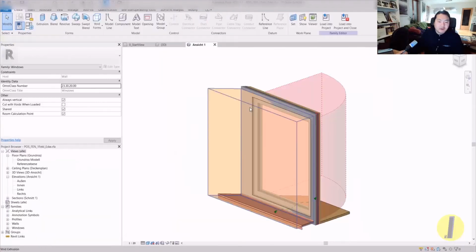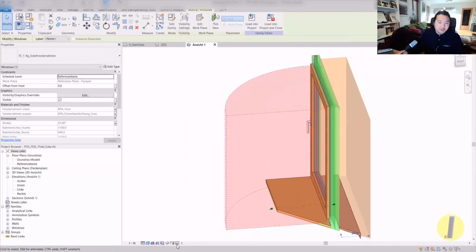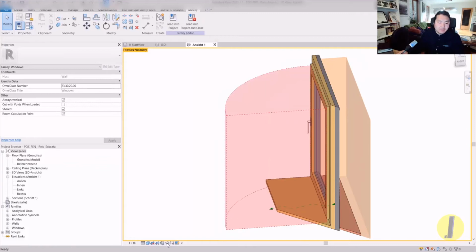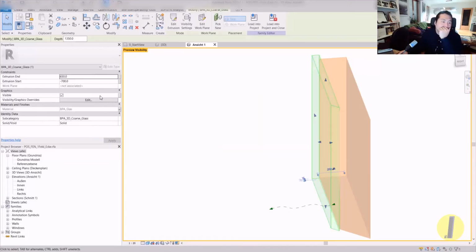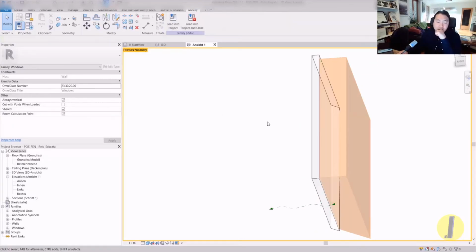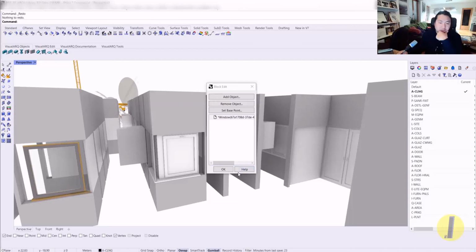So far I couldn't find a solution, unless maybe you nest this geometry into a family. So the nested family could solve it, which I have to test, because you can say in here extra parameter, you can say IFC export as not to export it. Perhaps it will work, but anyway, we know the problem.